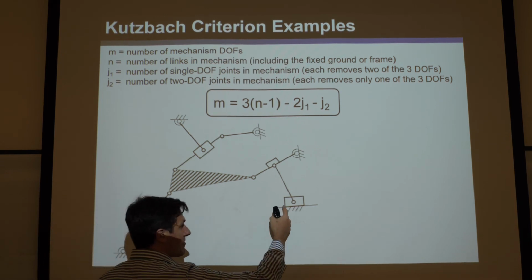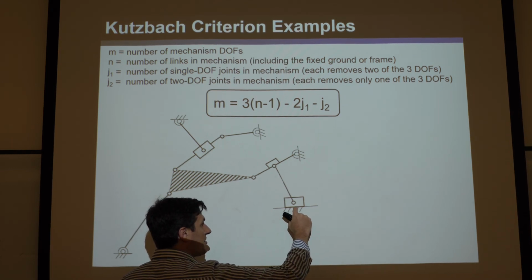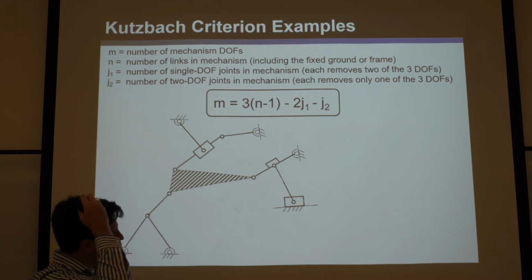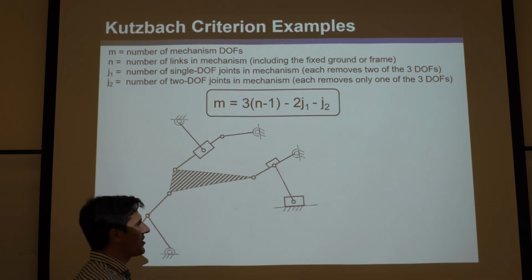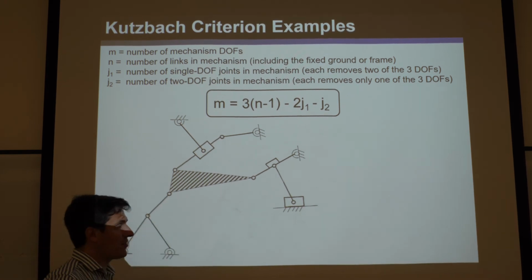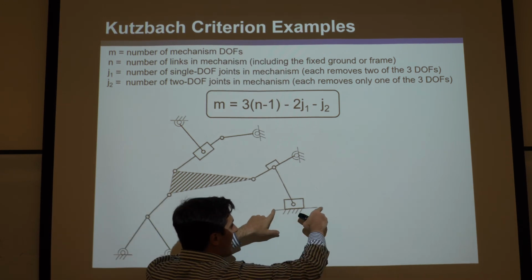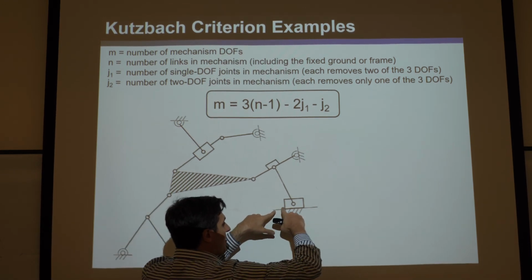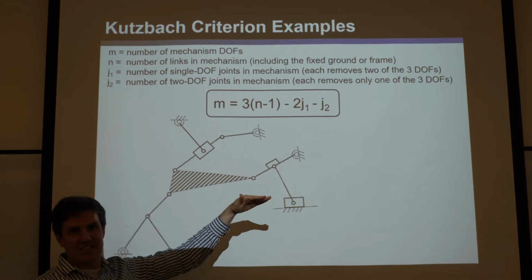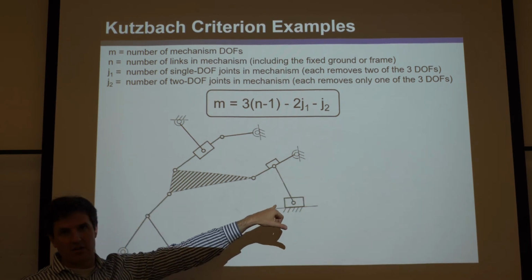Now this one, we have a box on a line with hatches, but those hatches are only below the square. Does that mean it's fixed? No, it's not. And I actually probably should have added that to the slide before, because the slide before had hatches going all the way on the sides as the only acceptable way to slide. But if you have a line that spills out beyond the edge there, no matter where you put the hatches, that means that the line itself is the link that's held fixed. But this is a box that slides with a prism joint on it, okay?